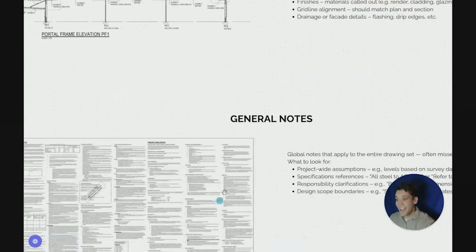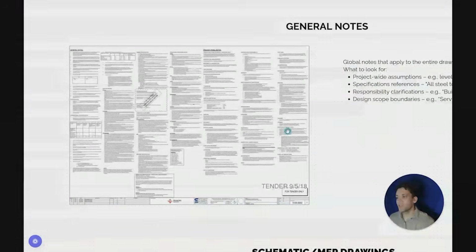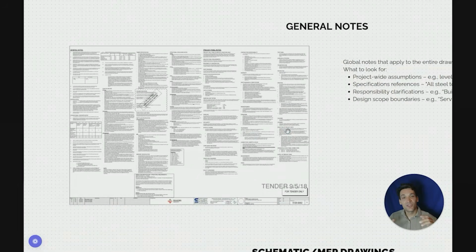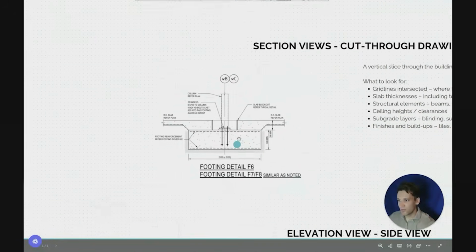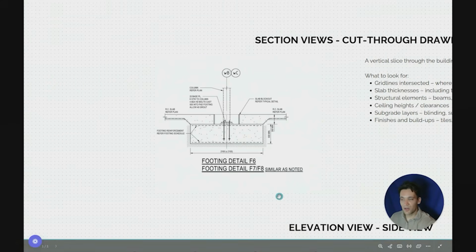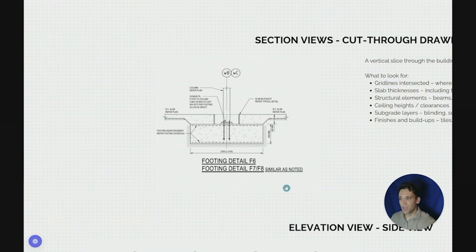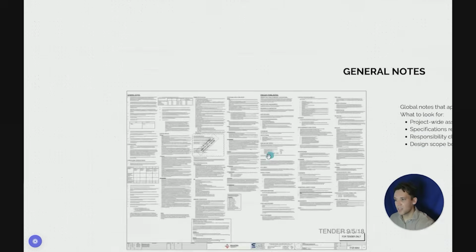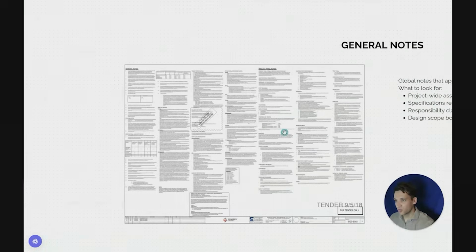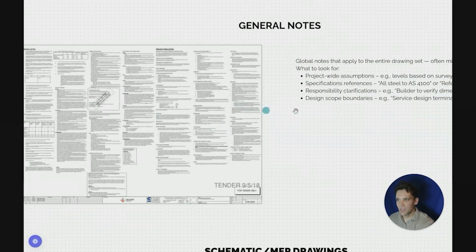Okay, next up we have general notes. So general notes aren't drawings, they're just notes that you need to read in conjunction with the drawing. So for example, if you've got this building that shows concrete foundations, there wouldn't be a note on every single drawing saying 32 MPa concrete that needs to get approved by the civil engineer with a specific mix design requirement. No, that'll be captured in the general notes of the drawings. We'll talk about the cover on reinforcement. It's basically to prevent repeating information on every single drawing.